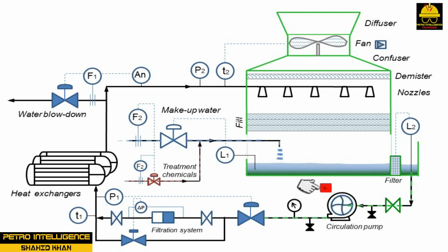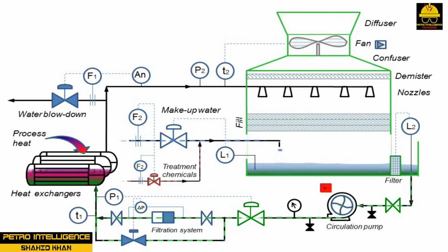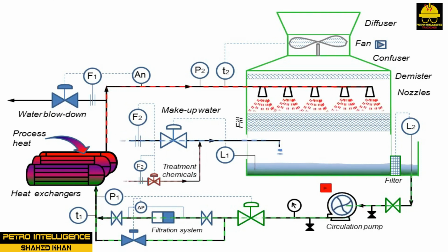The recirculating cooling water concentration ratio is designed for a minimum of 5 cycles and is controlled by blowdown. Continuous blowdown is used to prevent buildup of dissolved components. The cycles of concentration are controlled at the blowdown valve on the basis of the recirculating water conductivity.